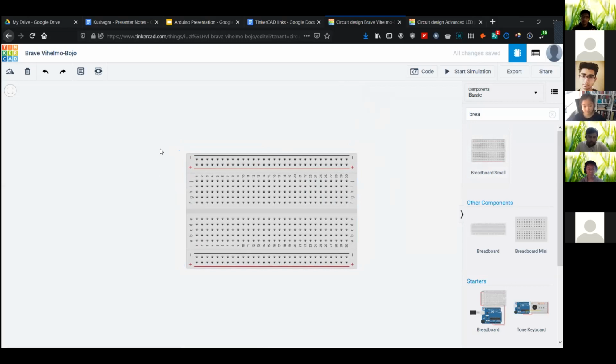So the breadboard, as I mentioned before, is used for prototyping. And on this breadboard, we can easily change the circuits that we create. But before that, we first need to understand how a breadboard is internally connected. All the holes on the topmost and bottommost rows are connected horizontally. What this means is that all of the pins highlighted in green are connected to each other. For this row, for the second row, and for the last two rows. These are generally used as power lanes to provide DC or AC voltage and a ground.